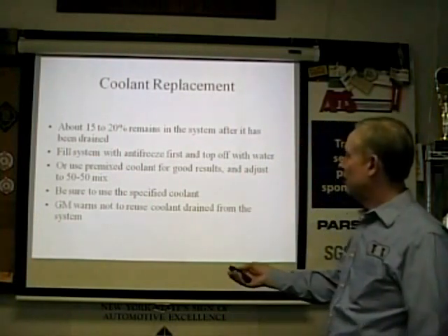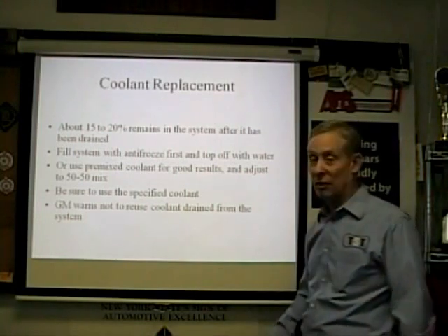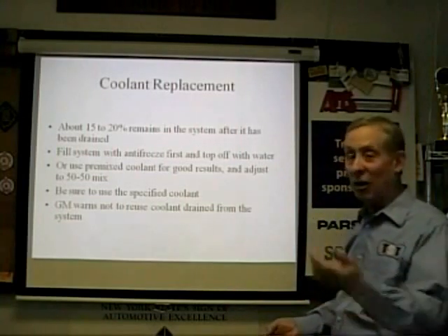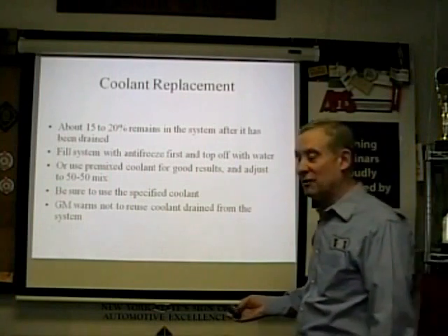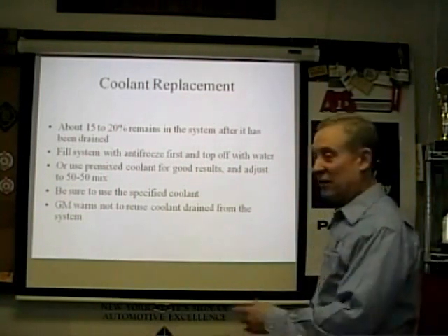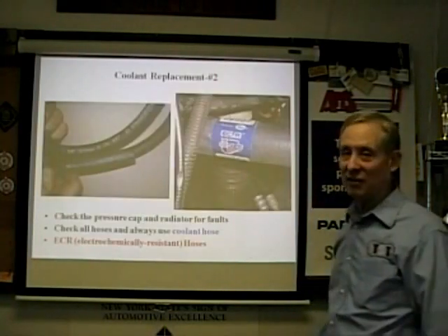All right. GM says don't reuse the coolant drained from the system. I think that's a general rule. Pierre recommends don't reuse coolant. If you take it out, throw it out. Gone. It's like the old rule about spark plugs. If you drop it twice, the second time in the garbage can. In this case, don't use coolant again. Drop it in the recycling.